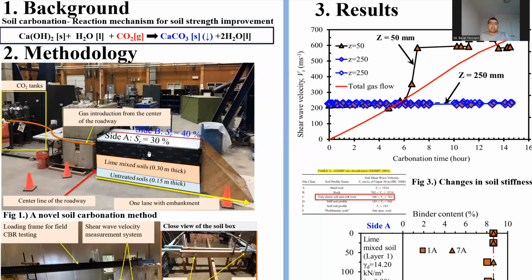The box is constructed with a silty material, and that material is classified as per ASTM as ML, which is highly frost susceptible material.